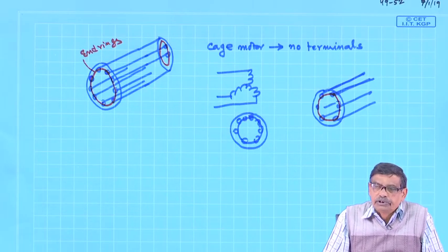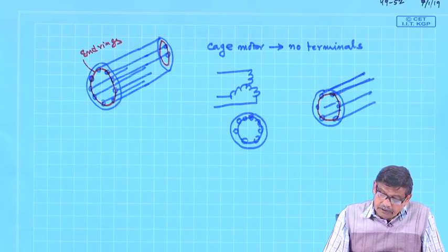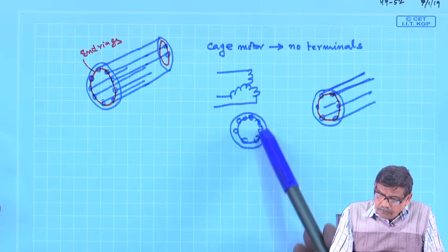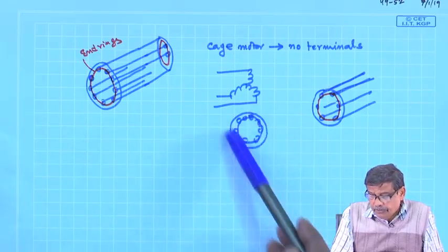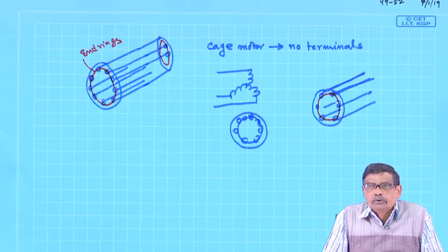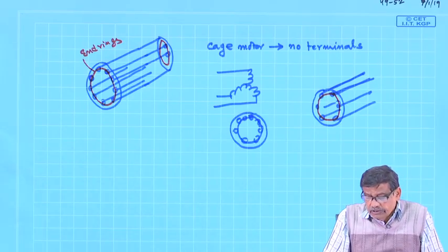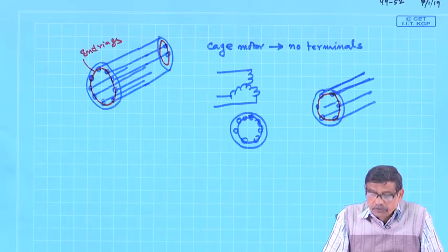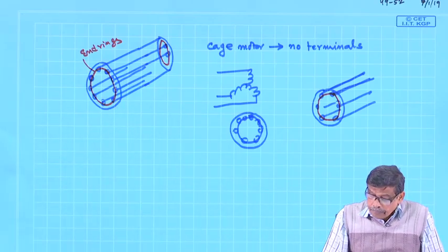That is the most crucial point, because the stator does not know what kind of polyphase winding the rotor is having. It is only interested to know whether it is developing the same number of poles or not. Based on that, the stator draws extra current from the supply when rotor current flows.